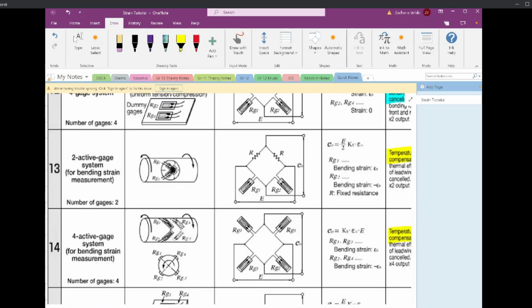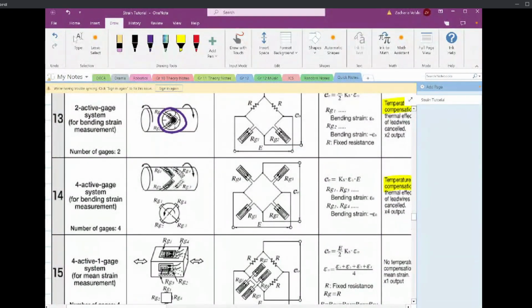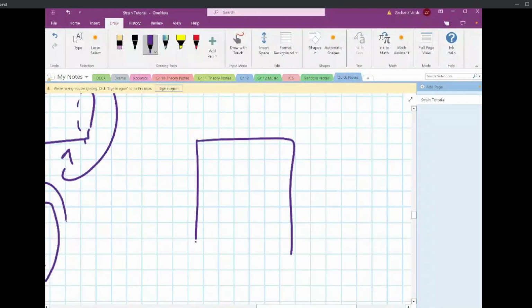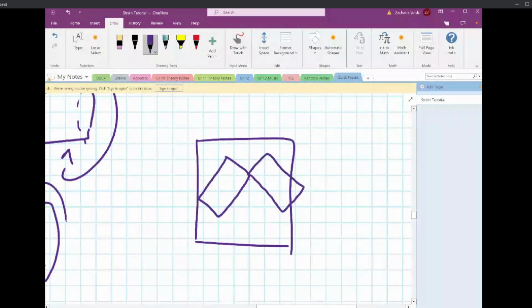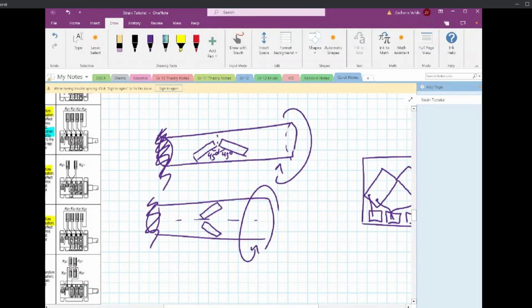These are gauge types that have built-in strain gauges already in those perfect angles for you. Those are really nice. I started experimenting with those this year as well for the axle on 23. Actually, it has this type. They look like big little squares. I got 2 of them. Kind of just like this. And they have 3 pads. This one goes here, this one goes here, this one goes here, and this one goes here. And it kind of makes bridge building already easy for you because they already set up half the compensation, so you don't need to wire as much.